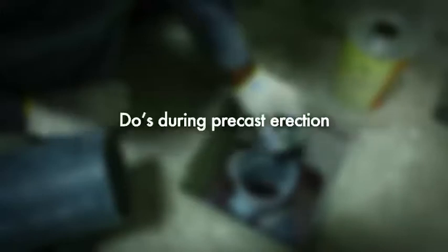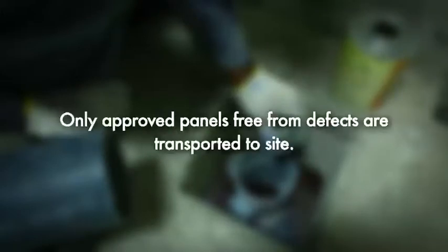Do's during precast erection. Only approved panels free from defects can be transported to the site. Elements should be demolded or shifted only after achieving the required strength. Check the room dimension, plumb and alignment of wall panels before joint grouting. Check the slab level and electrical connection before stitch concreting.